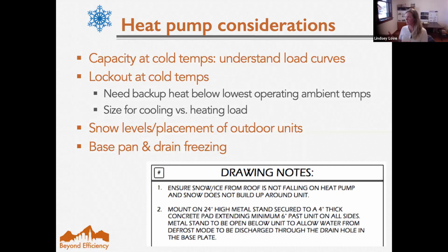But with the use of a refrigerant, it takes the heat from that source, whatever it can extract, and then applies it to the air or water that will then be distributed into the space. So the efficiency works really well when the differential between the source and the ideal air temperature is very low. And when the temperature gets very cold outside, the ideal temp stays here, but the efficiency really drops because it has to make up this huge gap.